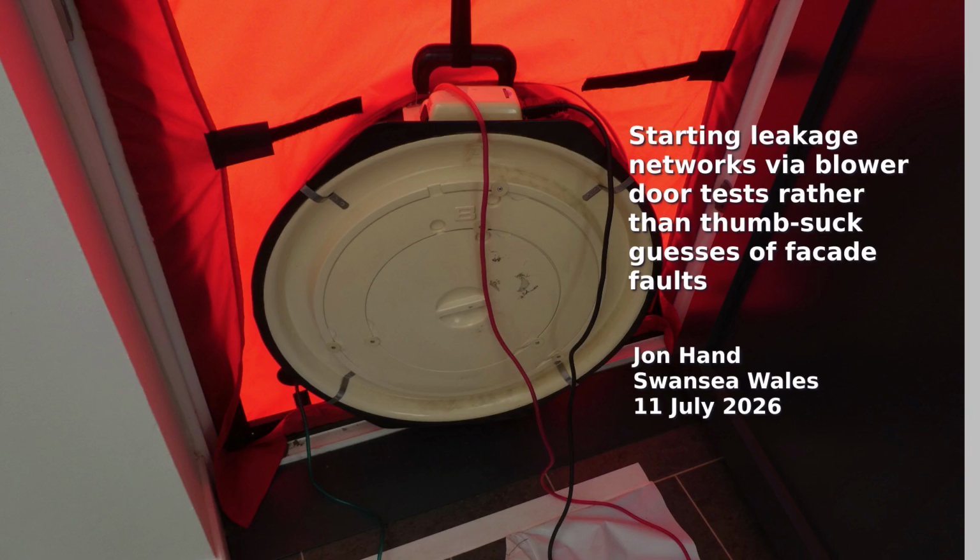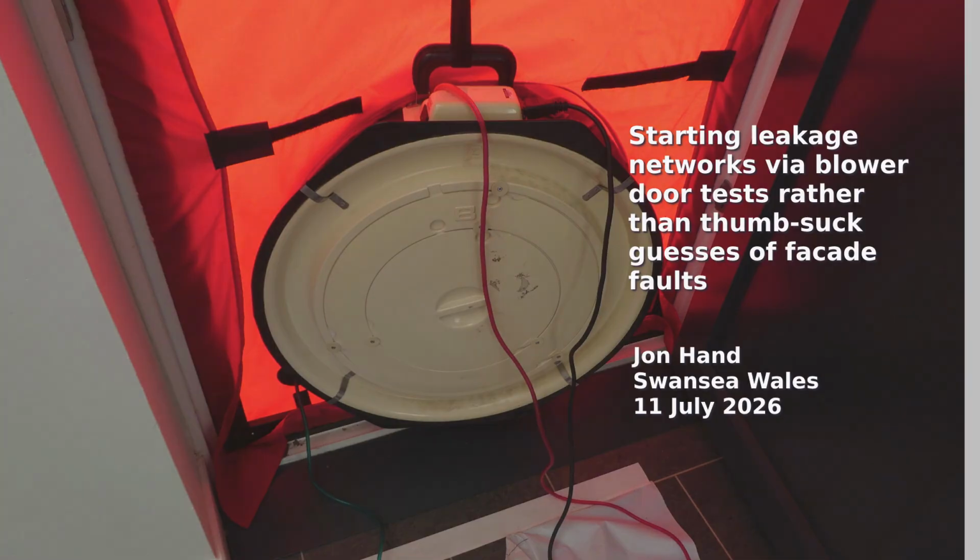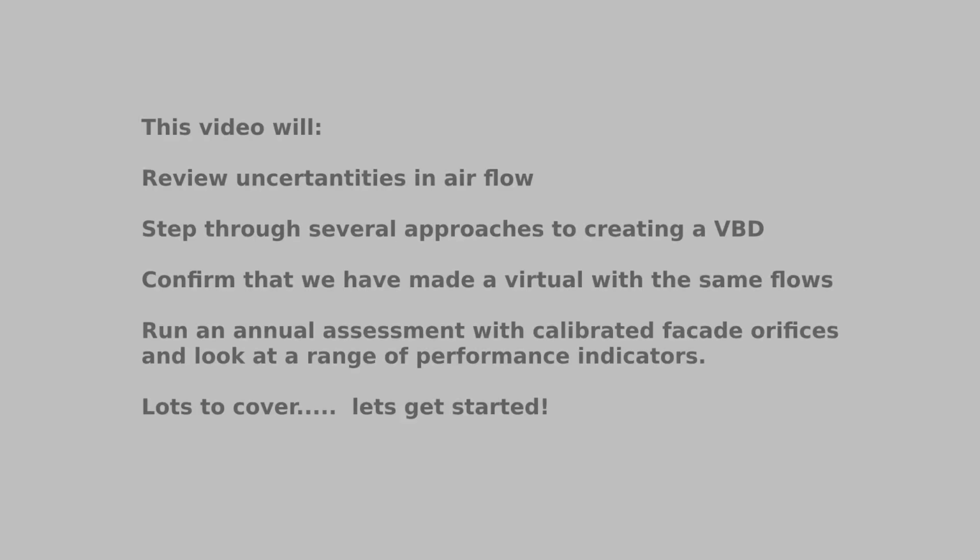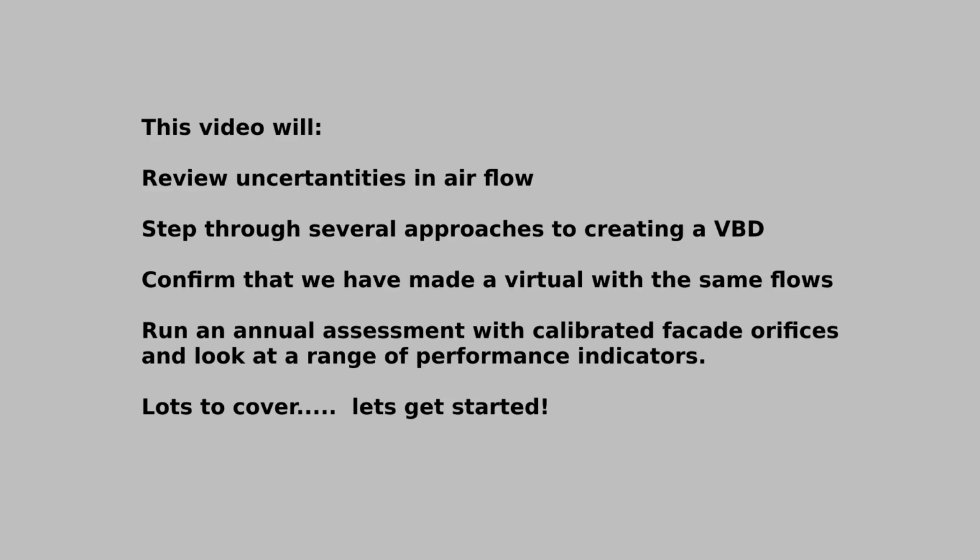This video applies blower door pressure test measurements to the initial setup of air leakage paths in a numerical simulation model. What we want to do is create a virtual blower door test, after which the facade orifices are used to assess infiltration risk. A bit of background.